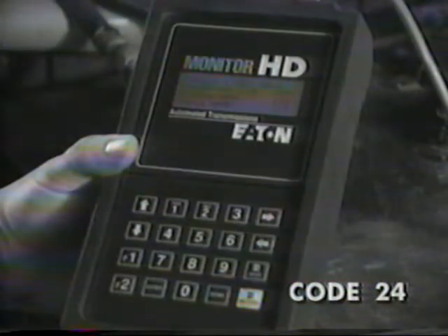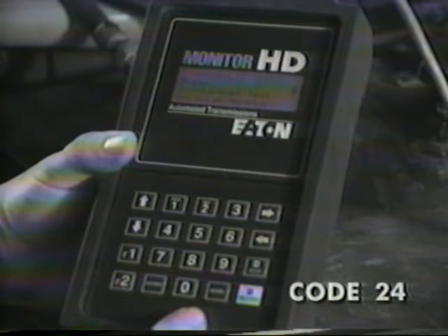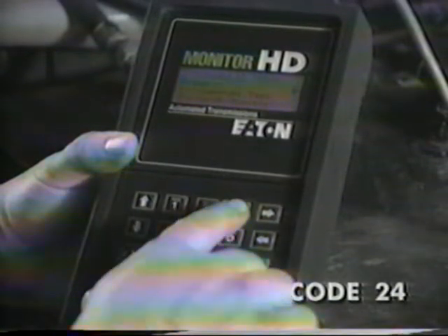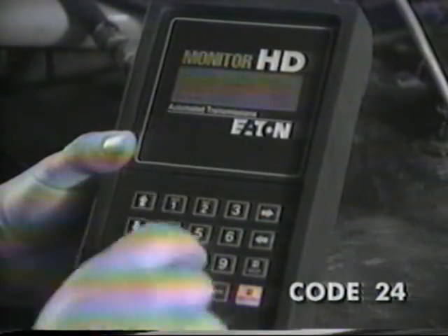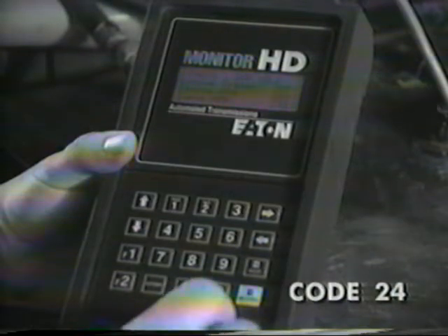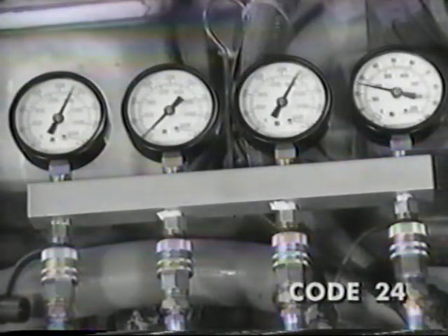If everything's okay, press Mode on your handheld tester to go back to the hydraulic test menu. Select 3 to access the lockup clutch test from the menu. Press 1 and press and hold 1 again as you observe the gauges. Main pressure should be 225 to 255 psi or 1550 to 1725 kPa.